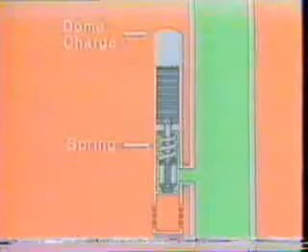Most manufacturers of this type of valve charge the dome only when high valve setting pressures require a supplement to the spring force. In this case, because of the large bellows area, it is the tubing pressure rather than the casing pressure which controls the operation of the valve. For this reason, it is called a fluid-operated valve. It requires a decrease in tubing pressure to close.